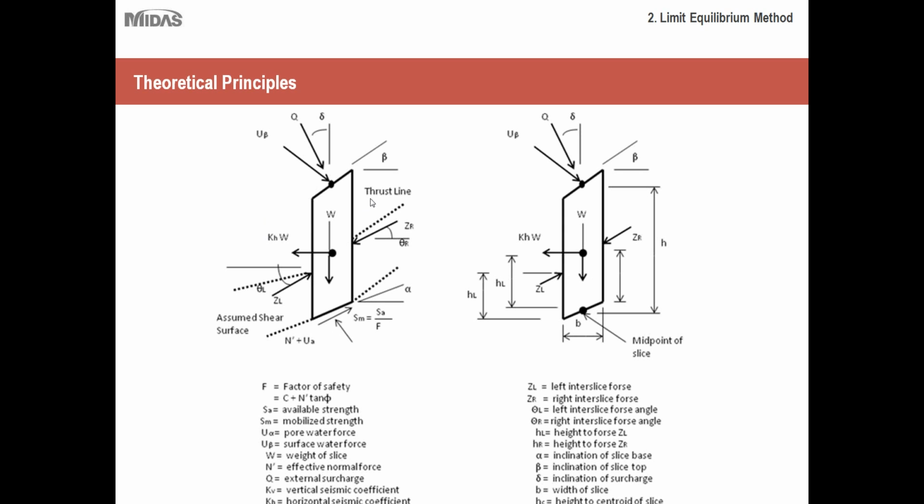Okay, so just to go further into the method of slices, I won't go into each of these individual forces, but I hope this will help you gain a greater appreciation of what these programs do for you. As you can see, there are all these forces that are taken into account when you're doing the limit equilibrium method.